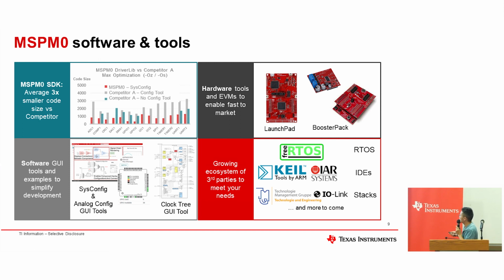For the LaunchPad, as you can see, there are two main devices here. The upper one is our debugger, the XDS110. You can just connect the port with a USB cable to the PC, and then you can get started to debug or code the device. So that is very easy to use hardware.